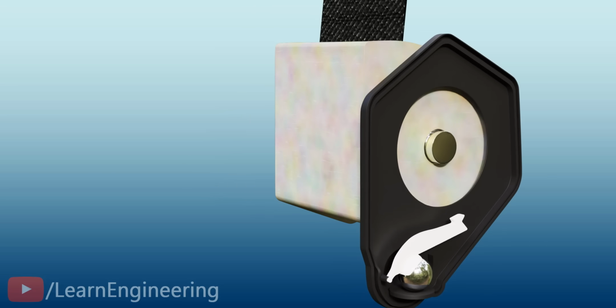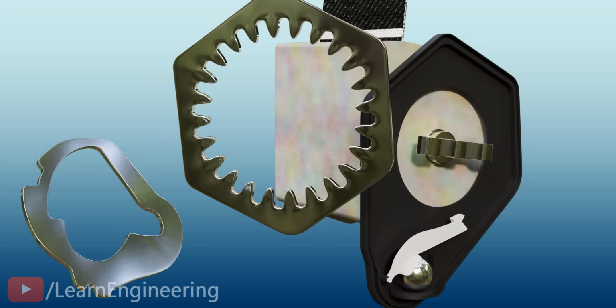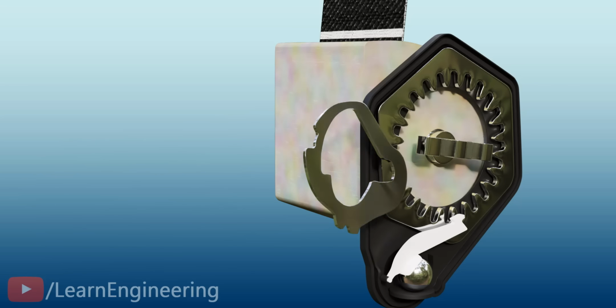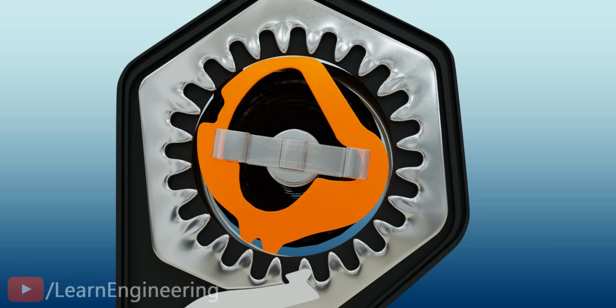This speed-based locking mechanism can be achieved with the help of a few new components. First, a central piece is fitted to the webbing shaft, and an internal gear is fixed by attaching it to the frame. Another piece sits over the central piece. Let's give it an orange color. The interesting thing is that the orange piece is not tightly fitted to the central piece. It is slightly loose and free to move, as shown.